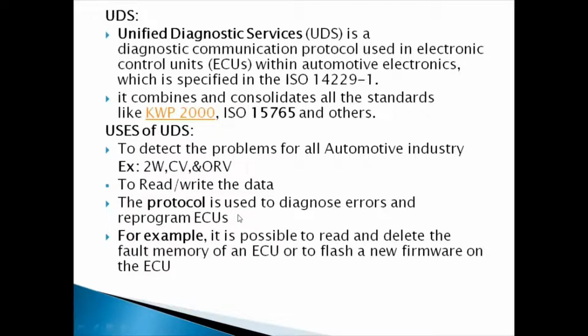In the secondary bootloader itself, all the features of the ECU are there, right? In this they implemented all the applications. Applications are nothing but different features. Once we load those files, there is a download option. We just have to click download.